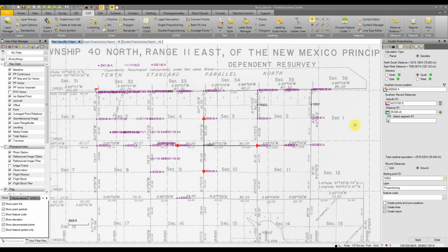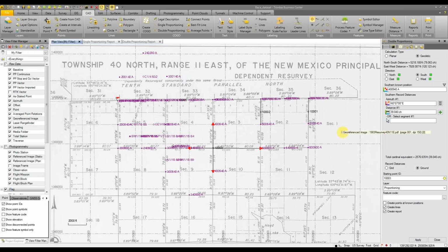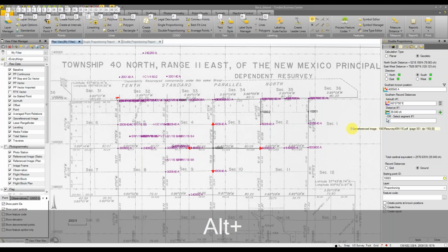You can use more points than 3. Then I believe it'll use least squares in order to best fit the image. Correct, that's correct. But 3 is the minimum in order to solve for the 3 unknowns in positioning the image. Hope that answers your question, Mel. Any other questions? No, so far so good. Very easy to answer at least.